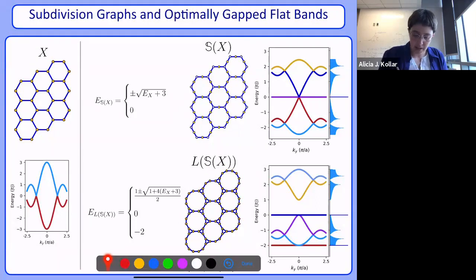this structure here. And now this is a special graph because it's 3 regular, ignore the edges, but every site in the middle has 3 neighbors. That makes it very easy for us to make in hardware, but it's a 3 regular line graph. And so that means that if you compute the bands, or this is actually over here, the density of states, it has no eigenvalues below -2. And so we can use this structure as our original hardware layout.